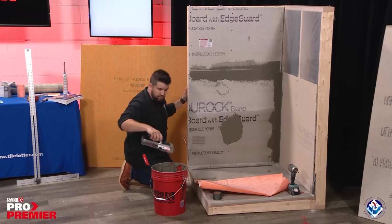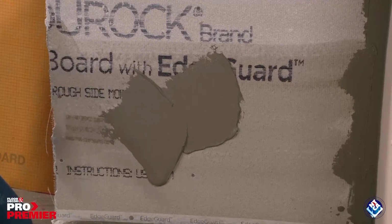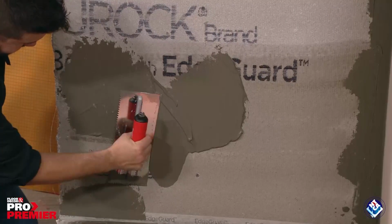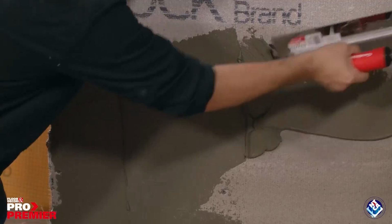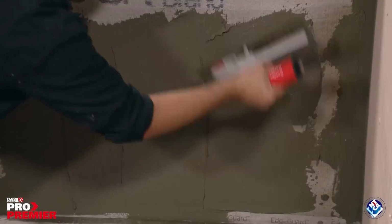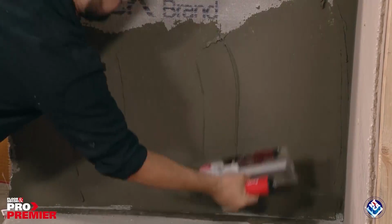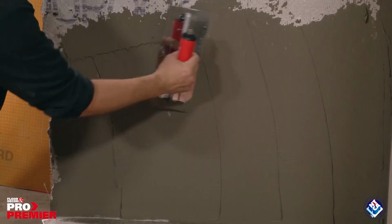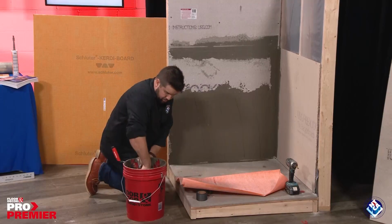So I'm going to apply a little bit of mortar to my substrate, and then once again we're going to use that flat side of the trowel, and we're going to key in this mortar. I've got that keyed in. We're going to apply some more mortar.